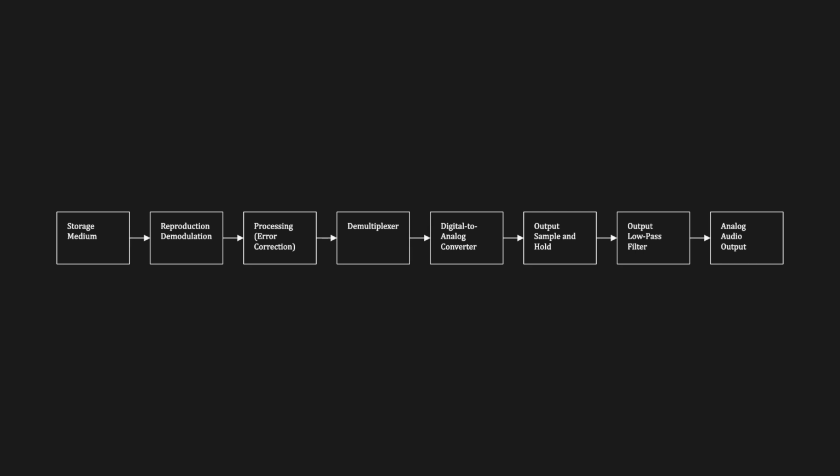The encoded audio data is then separated, demultiplexed, and converted into NRZ, non-return to zero code, where signal levels represent binary values. This makes the data readable for further processing. Demultiplexing also restores the parallel format of the original data. The circuit gathers incoming serial bits and outputs full words of data at once.